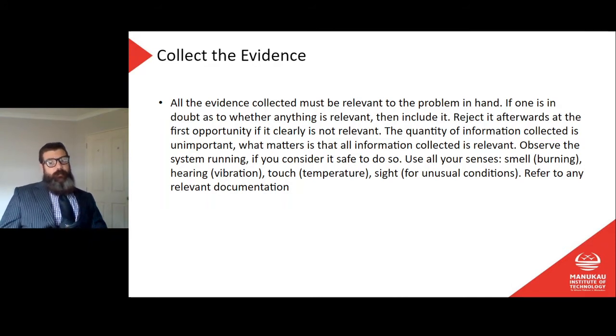The quantity of information collected is unimportant. What matters is that all the information collected is relevant. We don't want to include anything that is not relevant to us, because that's going to lead us down the wrong track. Observe the system running if you consider it safe to do so.